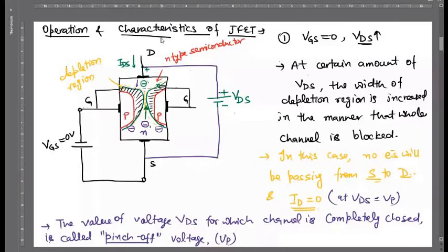Okay, now tell me, is there any doubt? Whatever you write N, that is N channel. Is there also N-type semiconductor? This is N-type semiconductor, and this region is behaving as channel for charge carrier, and we made two diffusions of P-type in different sides of this N channel or N-type semiconductor slab.